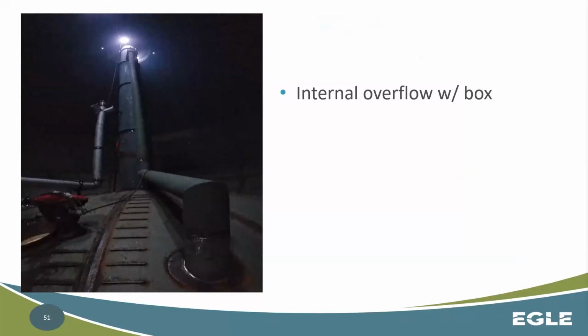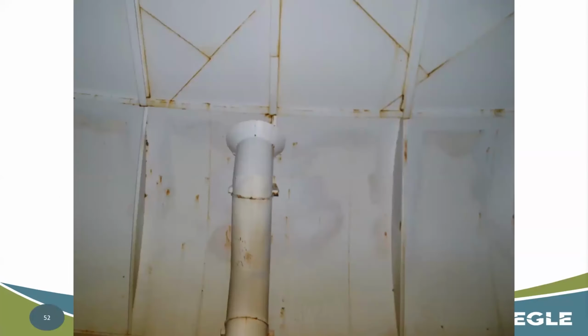Okay, so this is another example of a situation. So, weir box up here. Here's your flow. Here's your inlet over here as well. Here's your hatch that they came up through. So this could be a situation where winter goes along, and you have water rising up for whatever reason. Maybe somebody didn't pay attention or the telemetry failed or something. The pumps are still running, and now you have ice caking at the top, and now you're not getting that overflow. Okay, so that's an example of making sure your design is proper, making sure your design will adequately address whatever situations you might run into.